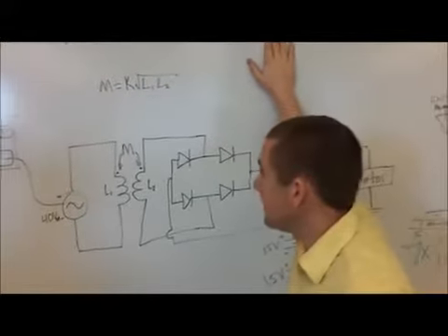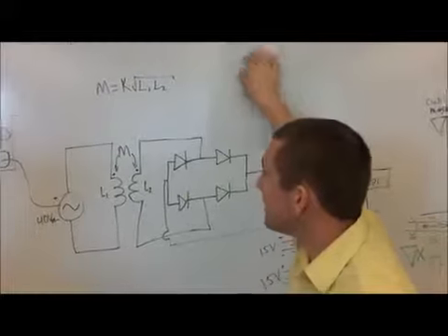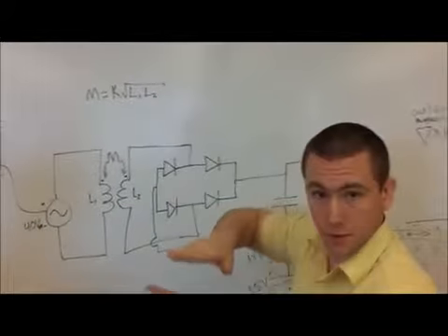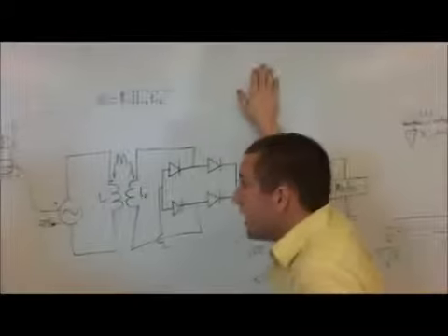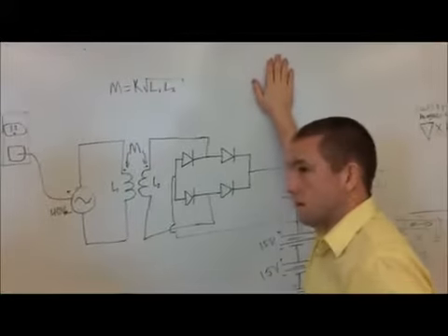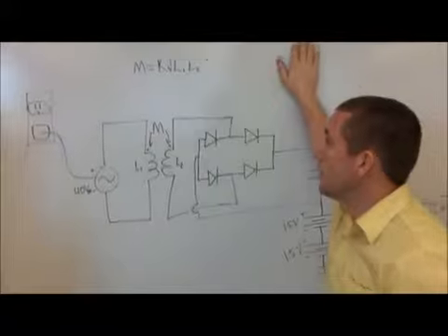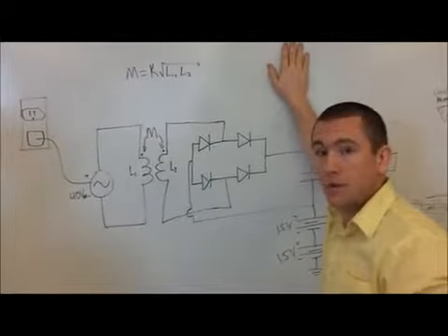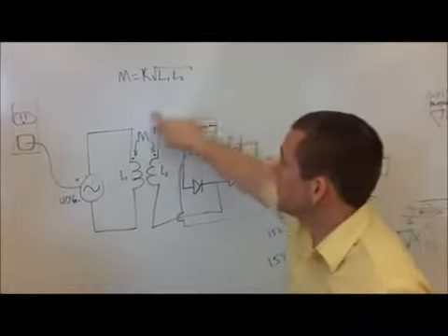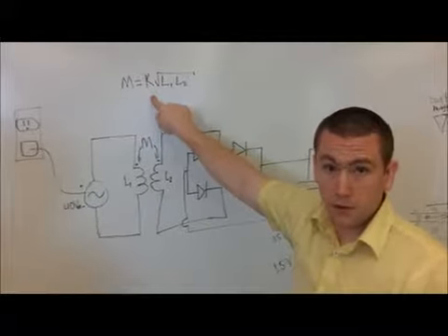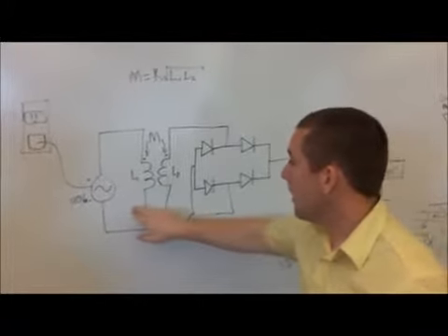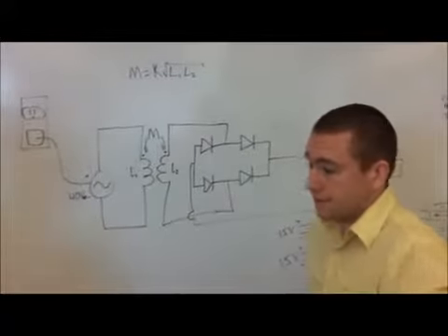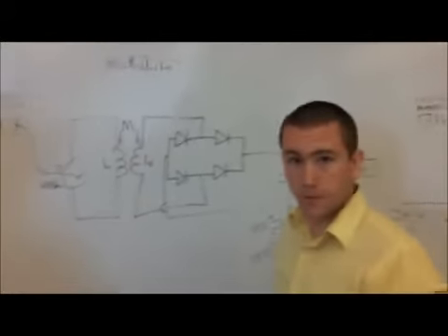We've done a lot of different things to maximize that by increasing or decreasing the distance between the two coils, and changing the size and the shape of the coils and the cores that they use. But with not sharing a common core, we're just having too much trouble keeping that value high. So the amount of power that's transferred from the primary to the secondary side is really tiny. Really tiny.